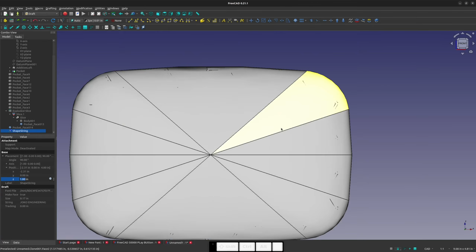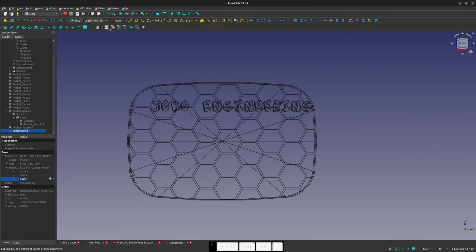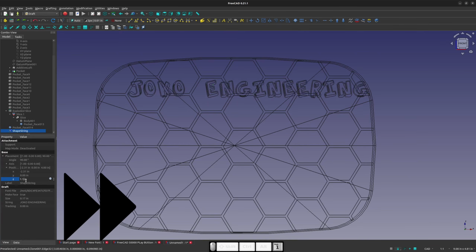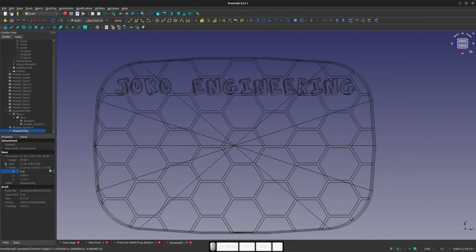It's my Z that I want, and of course I can't see my shape string because it's behind the play button. But I can always change my view to wireframe. And now I can start to see the particulars of my view. So I'll just enter points until I get something that I think looks really good. I think that looks about right.